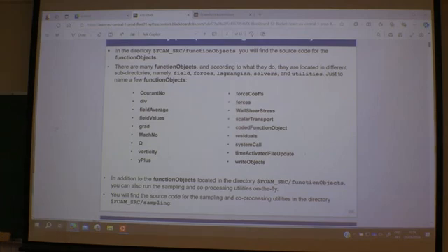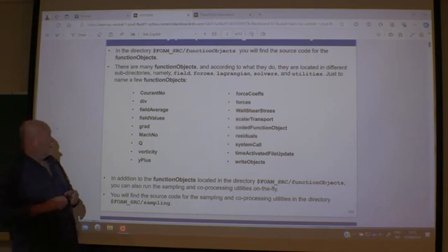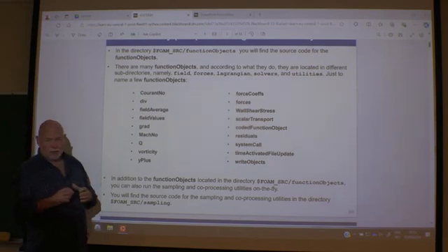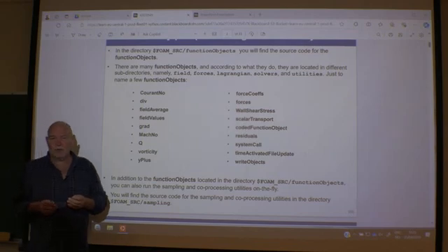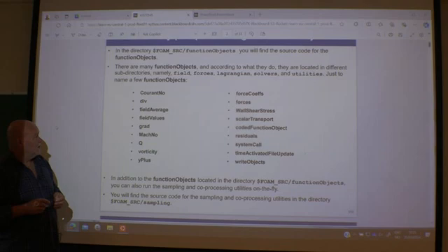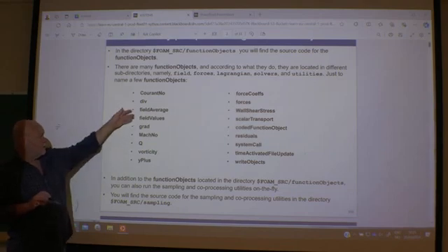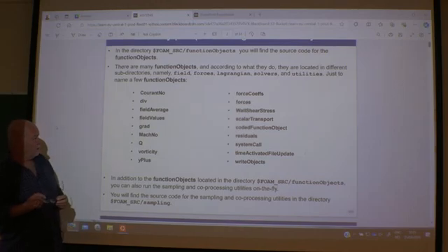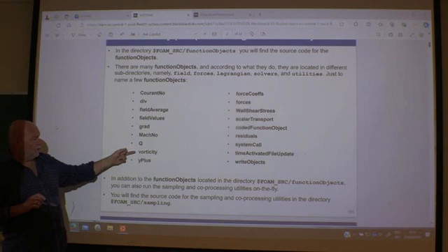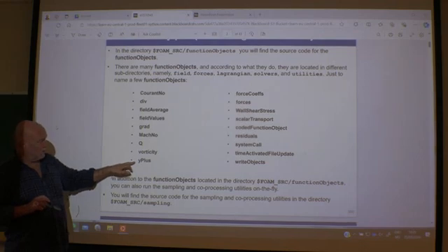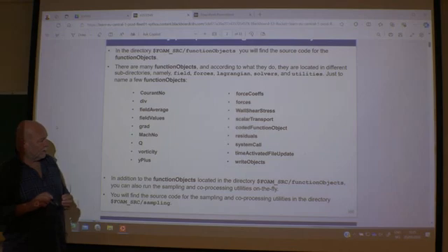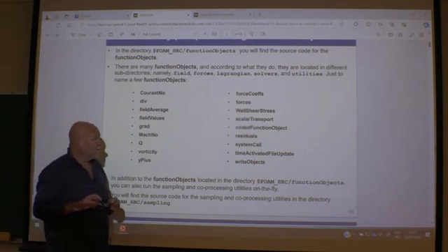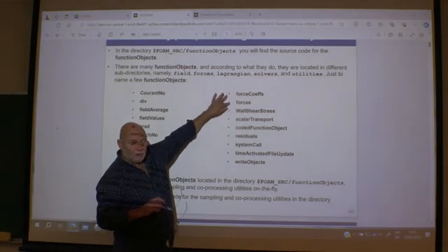So here, for instance, you have a whole bunch of these function objects that you can include into the controlDict. And well, the Courant number, normally not a problem. We will have that one displayed anyhow when you're doing a transient simulation. Finding field averages, field values, okay, maybe not so nice. Vorticity, that's something we are going to look at today. Y plus, always nice to know. So you can automatically get the Y plus while simulating. And also these two, something we are going to look at.